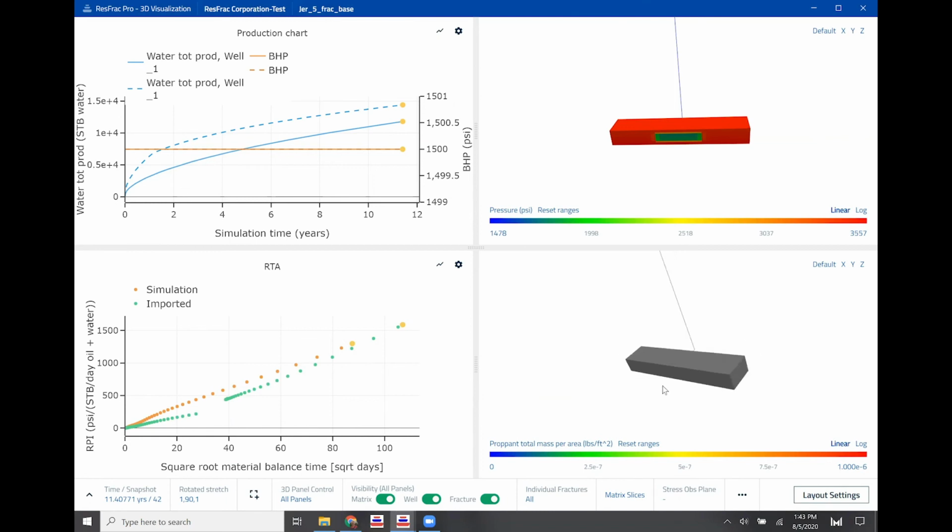In the 3D viewer, clicking and dragging will be a free manipulation where you can rotate the image in any manner. If you hold Control and click, you rotate around a single axis. If you hold Shift and click, it will translate the image as you drag your mouse. If you hold Control and Shift and click, it'll zoom in and out. In this way, you can easily position a 3D image to look at the exact angle that you would like to view.